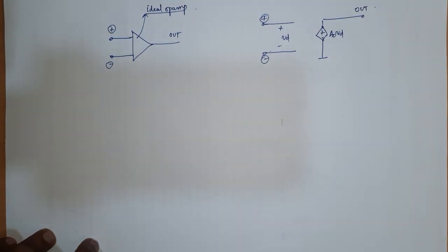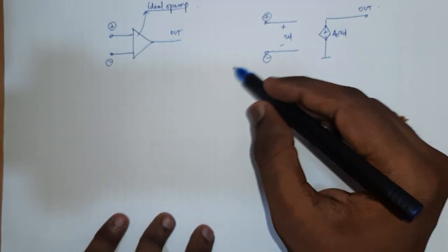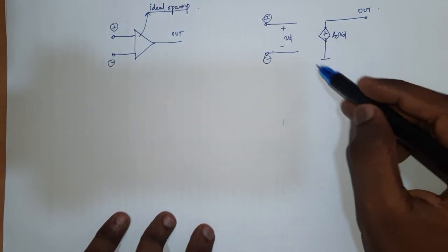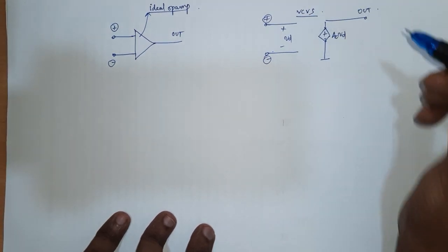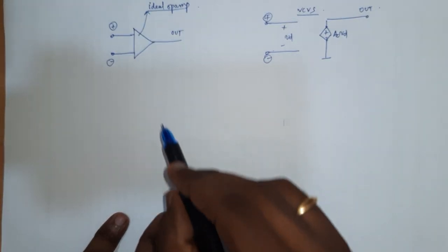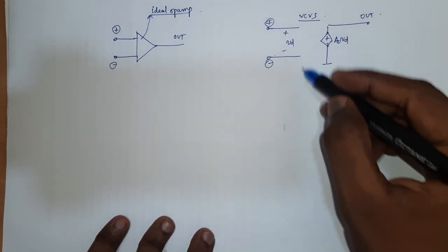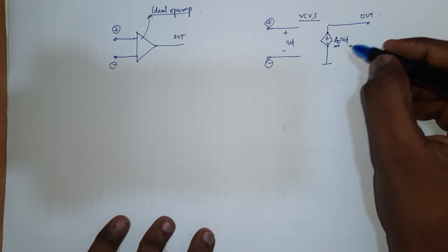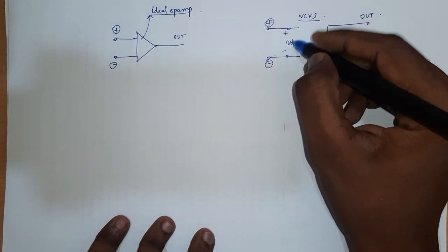Okay, so this is exactly same as this one, just that I have considered a model for an ideal op-amp. This is basically the model for the op-amp, which is a voltage control voltage source, and as far as it's an ideal op-amp, I need not go through this particular scenario of A0 being there and VD being there and all these things, because I know that this voltage and this voltage are the same.